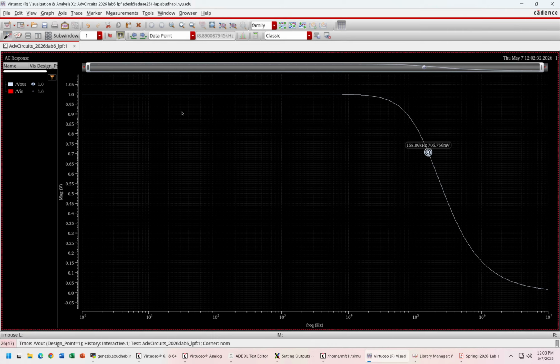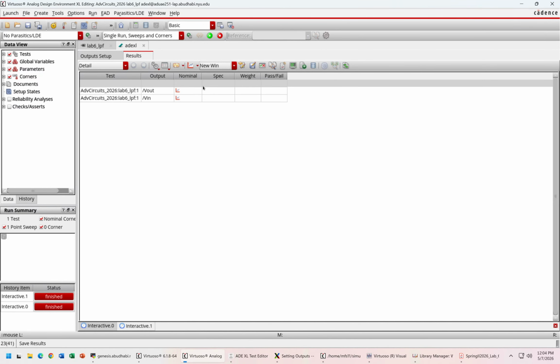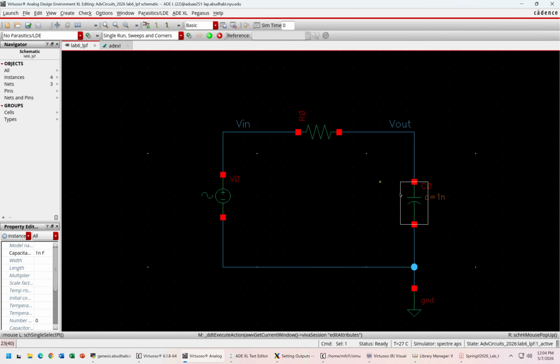All right, now if I want to see how the system responds to another different value, for example, then all I have to do is go and change the C value again, and then this cycle will continue. Instead of that, today we are learning the parametric sweep. In parametric sweep, I want to cycle the values of C from 1 nano to 10 nano to 100 nano, different values, and I want to see, by keeping the R value the same, how my system responds.